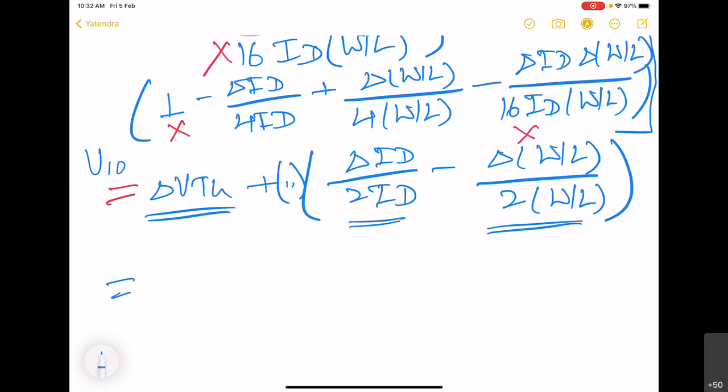So this we want to represent as a function of the RD and its difference, because this is another location where the two halves of the differential amplifier become distinct because of the mismatch in the RD, in addition to W by L or threshold voltage. So now we have to find how to substitute this in terms of RD.